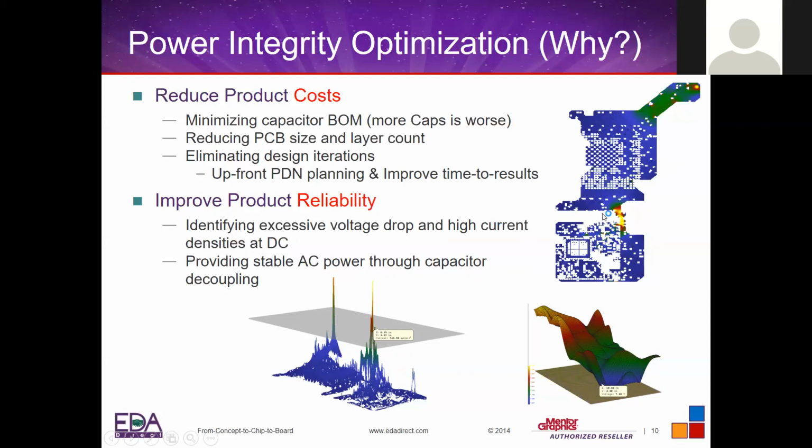Okay, and you may have a narrow channel like this, where all of the current has to be passed back and forth between the regulator on the top and the big chip on the bottom here. And through this little segment, current density might be very high. So let's say you have an FPGA design down here, and you're running at 400 megahertz and everything's working fine. And later on, you increase the speed of this FPGA, just having changes internally, nothing outside on the board. And all of a sudden, because it's running faster, it's consuming more current, and it's stressing this path over here. And that might lead to intermittent failures.